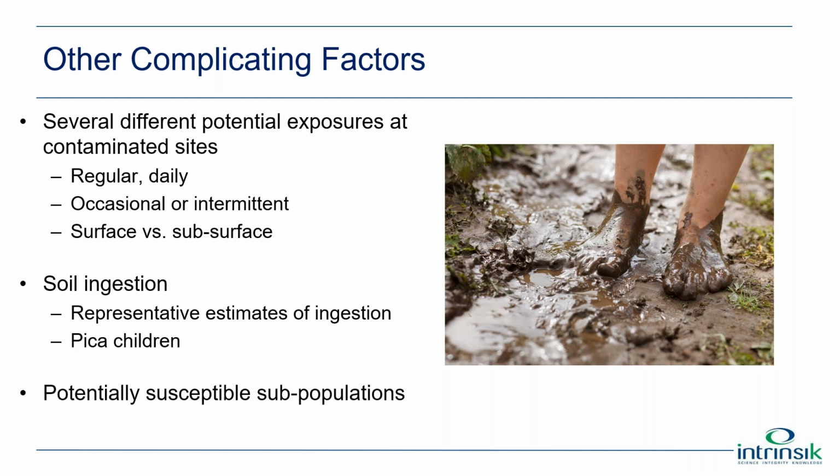Is the exposure regular or daily? Is the exposure occasional or intermittent, like a person that could come and do landscaping work a couple of times a week on a site that perhaps has some contamination? How would you estimate their exposure? What do you know about the chemical? Is that contamination present at the surface or at the subsurface? Is it something that's only relevant to a site worker that would be excavating soil with lots of PPE in place and risk management procedures, or is it a child that could be playing?